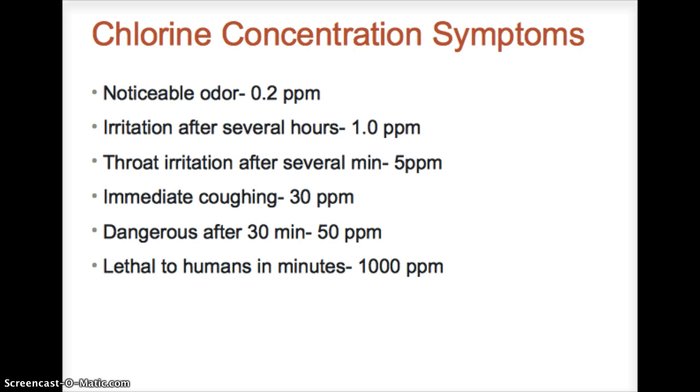The irritation after several hours would be in your throat at 1 ppm, 1 part per million. Throat irritation after several minutes at 5 ppm. Immediate coughing at 30 parts per million. Dangerous after 30 minutes, this would be at 50 parts per million, and lethal to humans in minutes at 1,000 parts per million.